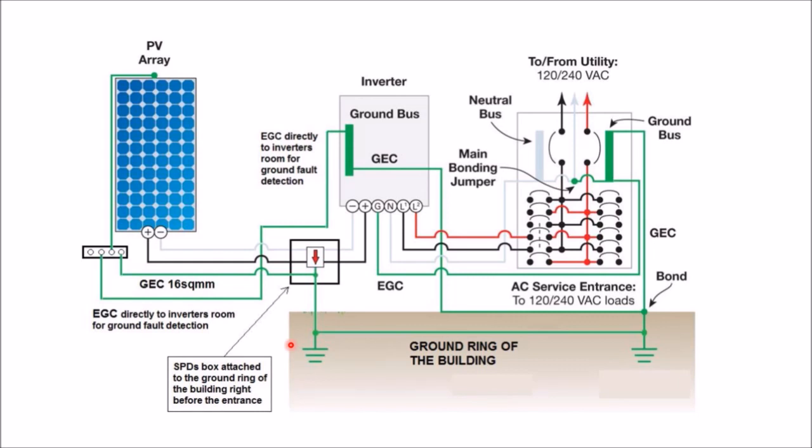You don't want that voltage staying hot on the module surface and then someone comes and touches it and electrocutes themselves. You don't want that voltage connecting to the rack and then connecting to the roof and then energizing the beams in the wall, and maybe the building is not connected to ground very well because it's on top of a concrete slab and it might not be that big of a building, so there might not be much surface area touching the slab, and then someone touches the wall of the building and electrocutes themselves. Now, you don't want any of that. You want a nice big thick piece of copper going up to the roof and touching your solar array, and that thick piece of copper coming down the sidewall and going straight into ground.